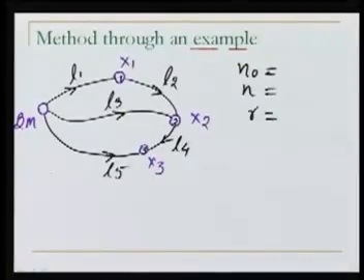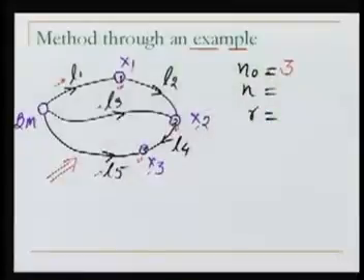So the job is to determine the RL of x1, x2 and x3. In this slide, point number 1, point number 2, point number 3 have RLs x1, x2 and x3. In order to determine these RLs, the minimum number of observations we need to carry out is L1, L3 and L5, only 3. By taking 3 observations this problem can be solved, but the solution will be unique, with no redundancy. So actually we go for more observations.